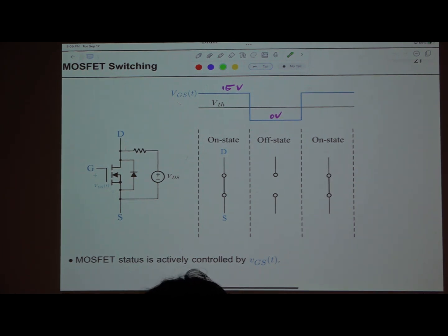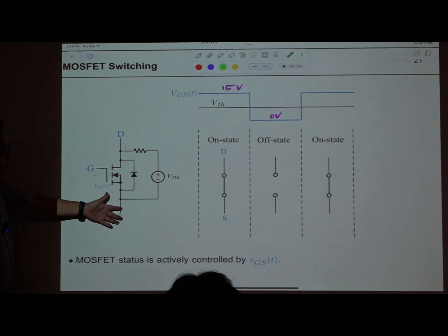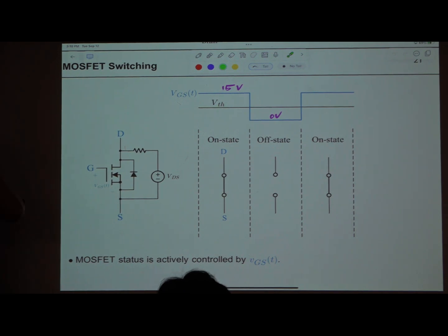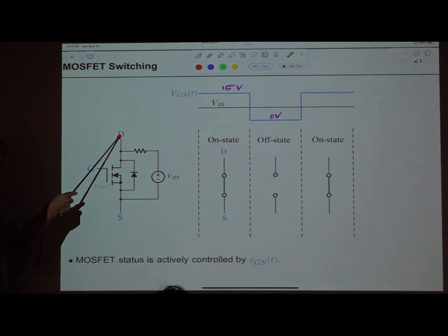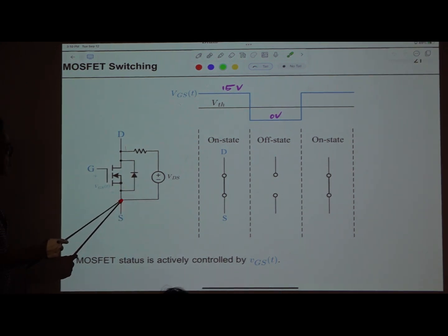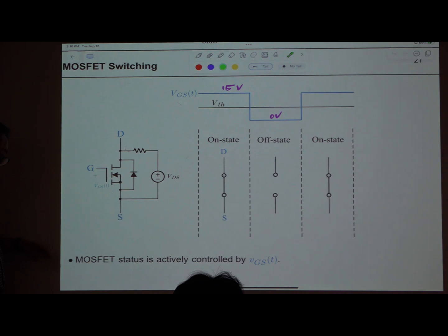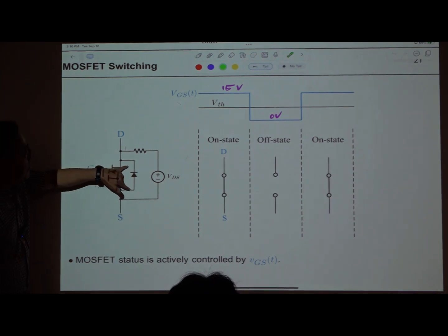But in some applications, this becomes positive and this becomes negative. Actually, one student asked about that situation. So I was thinking about that, and I'd like to give my answer. All right. Suppose this is positive and this is negative. The current will go through this. And this is the diode. The diode is not conducting any current until this voltage becomes 0.8, 0.7.